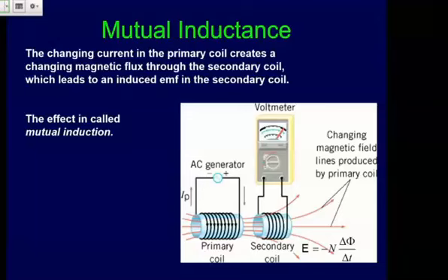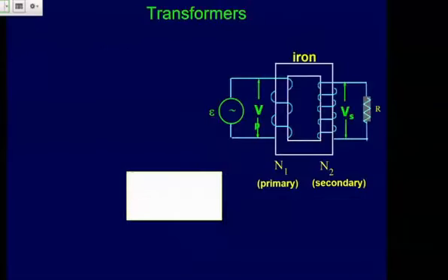So you're using the idea of Faraday's law. Here's how the pictures typically look. You have the primary and the secondary, and a piece of iron. The iron is the kind of material that redirects the magnetic field. Your primary source is an AC source, like the generator we were just talking about, so the current going here is changing back and forth. You create a changing magnetic flux, and the iron redelivers it over here, so you have the same flux over here as over there.